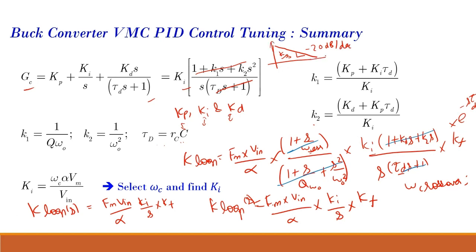At low frequency, your loop gain is very high, and at high frequency it is reducing. The frequency at which it crosses 0 dB is your crossover frequency, and based on it you get a certain phase margin, depending on how much phase was present. This is the phase margin test.